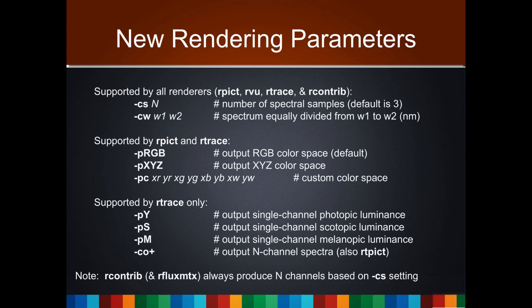Yeah, Alan, that's a good question. If you have, say, defined a material that you've only defined in the spectral range of 380 to 780, what happens if you're rendering outside that range? It all gets set to black, basically outside that range. It just assumes there's no reflectance or anything going on out there. And if you do a narrower rendering range than the material is defined, that chops off whatever data you gave it. Good question.